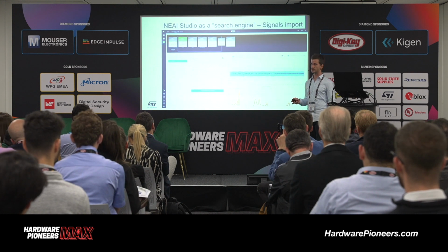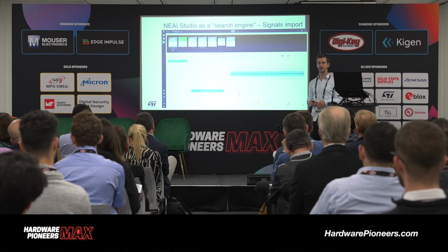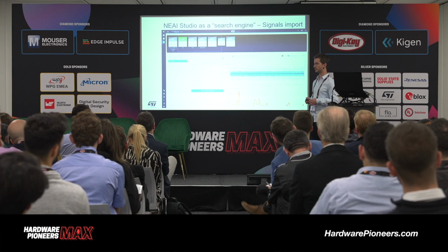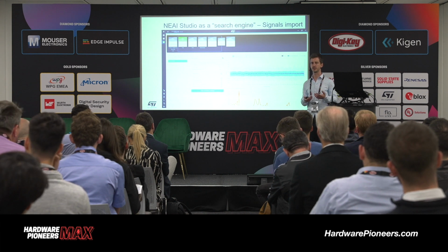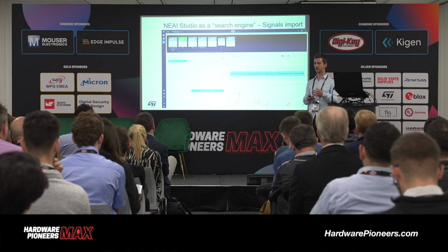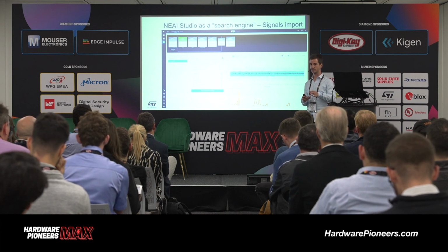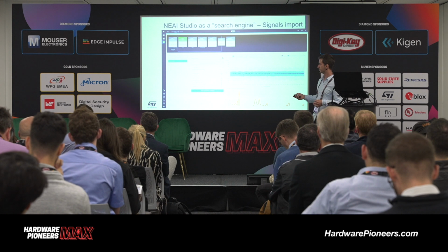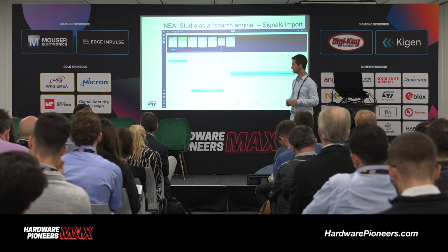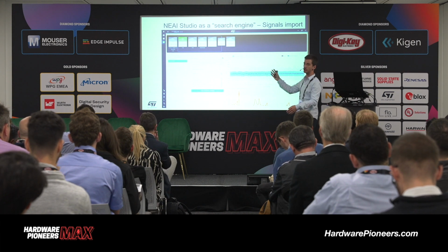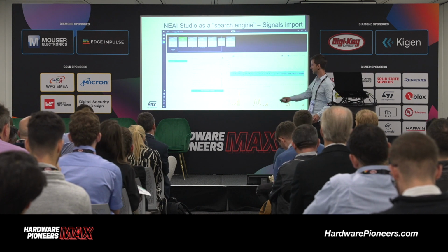Then you input some data. And here we're not talking about hundreds of thousands of data points. It's more about 100, or 50, or a couple of hundreds, depending on what you want to achieve, right? If you want to solve a very complex issue, maybe you need more granularity in your input data. So here we have 100 signal examples. So you see these are temporal slices of the vibration on 3 axes. And you have some FFT as well.